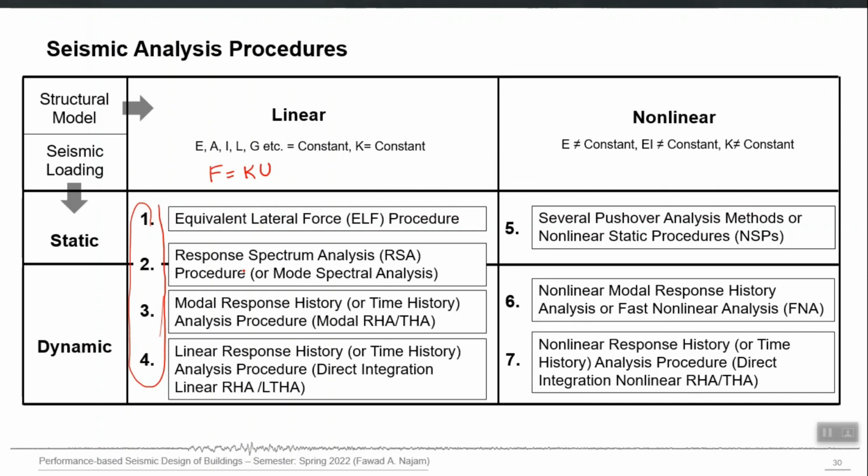So then there are some additional considerations when you apply that equivalent static force, reduced force. After that, there are some additional considerations which I will quickly go through today. In the nonlinear domain, we again have two categories, nonlinear static and nonlinear dynamic, right. In 5, 6, 7, actually 6 and 7 are the same method, the nonlinear dynamic method, but the calculation algorithm or procedure is different. Similarly, 3 and 4 is the same method, but the calculation procedure is different.